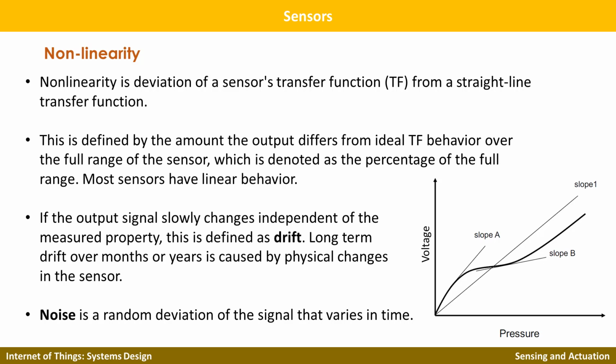As we discussed earlier, sometimes the graph doesn't seem exactly linear. So you try to create an approximation and then measure the difference between the ideal transfer function and the real one, and you create different functions to track different slopes and match in an approximate way.